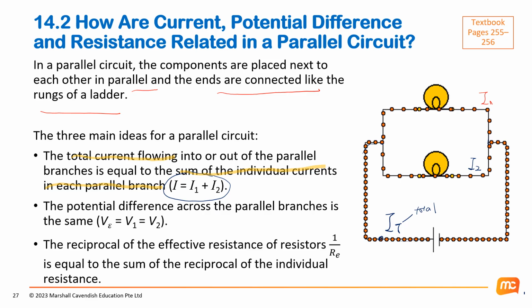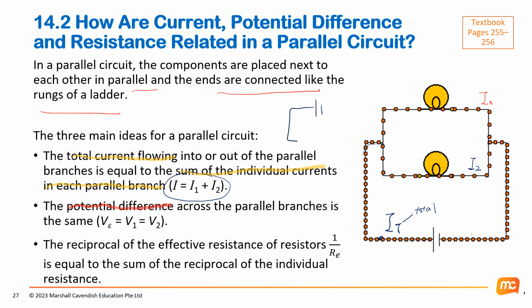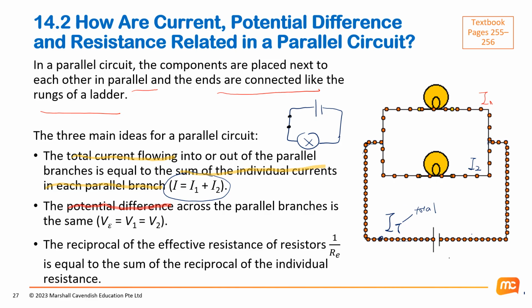And if you think about how the potential difference behaves, just now if you think about your series circuit, the video that was shown, if I take the potential difference across the same part of the wire, whereby there's nothing in between, no resistance, I should be getting 0 volt if I put a voltmeter across the same part of the wire.